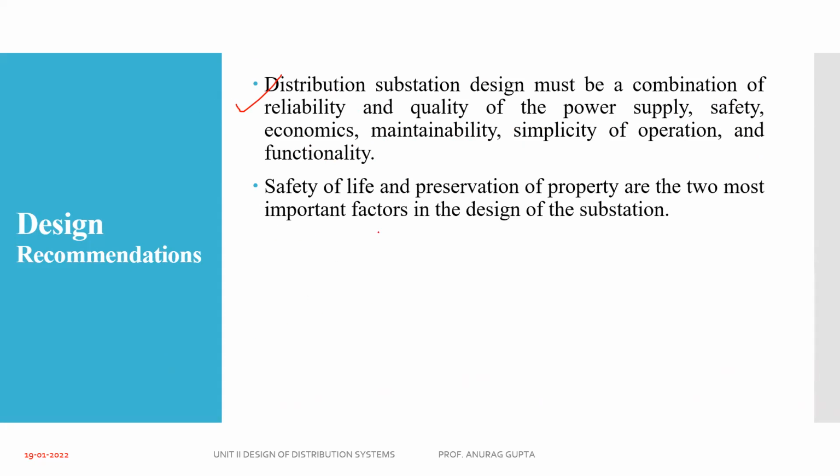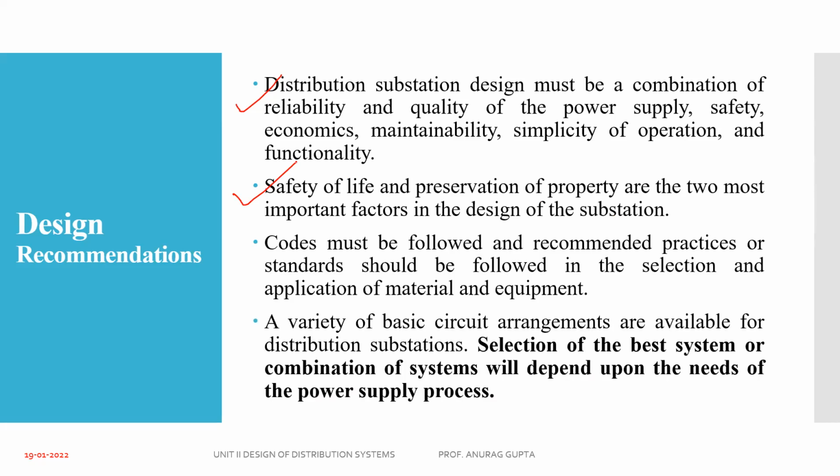Second, safety of life and preservation of property are the two most important factors in the design of a substation, because when we are designing substations, safety of life will of course be the most important factor. Safety of life means safety of human beings, safety of animals, safety from all environmental effects. Codes must be followed and recommended practice, and I have already given some IEEE or IEC codes for reference. Clear? So of course every distribution system design must follow some standard code, in terms of IEEE or IEC.